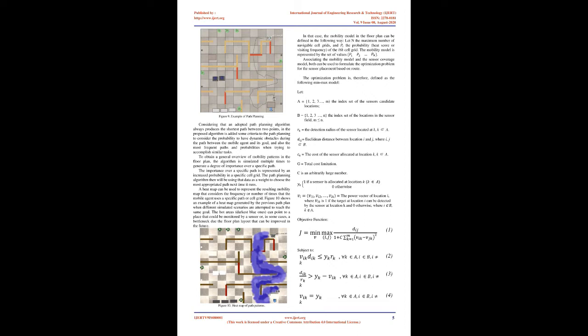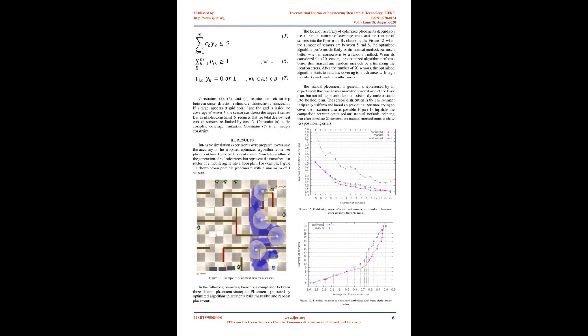The placement algorithm requires previous knowledge of the floor plan prior to sensor placement. Existent obstacles are then modeled by updating their detection probabilities for specific cell grids. For instance, if an object such as a wall is present in the line of sight from cell grid M to cell grid N, then the probability is set to 0, see Figure 6. Partial occlusion can also be modeled by setting the detection probability to a small value different from 0.